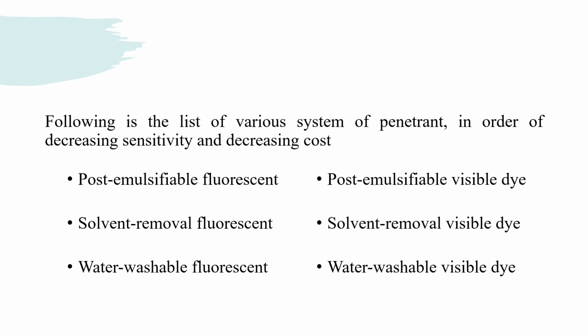So this is the list of the various systems of penetrant in order of decreasing sensitivity and decreasing cost. So high sensitivity and high cost is for post-emulsifiable fluorescent, and lower sensitivity and low cost compared to this is water washable visible dye.